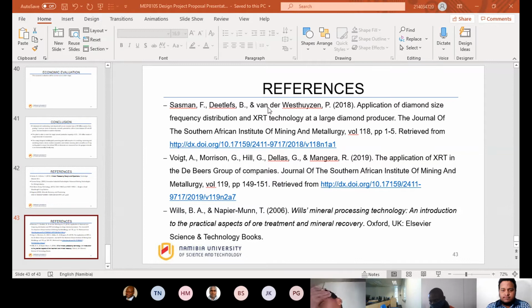So that will be, in terms of the surface arrangement of those fine materials that will be stamped as part of your gangue material that will be sent to your thickener. In terms of the chemistry from your test work, you would have a clear idea of how one is going to use the specific type of flocculant and coagulant.